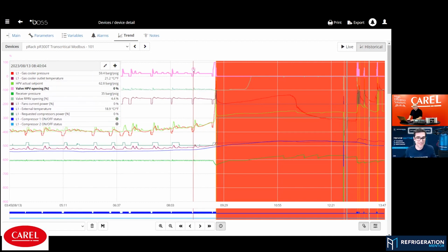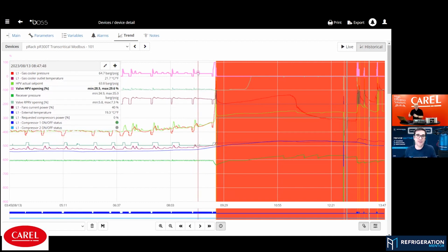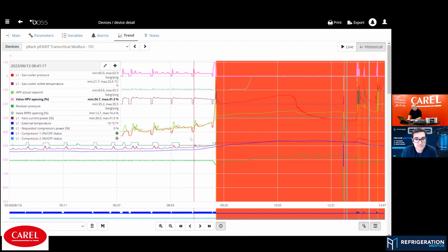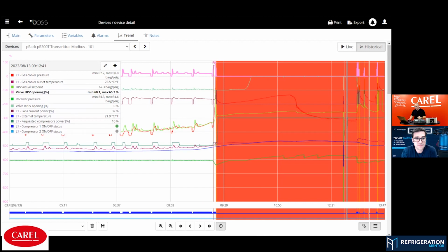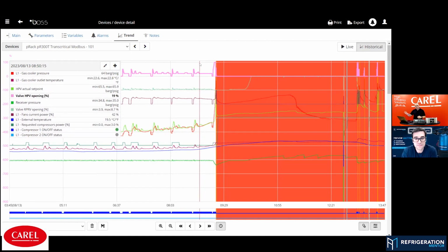You don't want to close for sure, because you're going to open those reliefs, and you don't want it wide open. Why is it wide open? Is it not getting enough gas? Is it short? There could be lots of different reasons. Exactly. And we see something here: at this point the valve opens up to 100%. Yeah, that's not okay. And it's directly before we have our alarms. So here's something we have to take a closer look at.